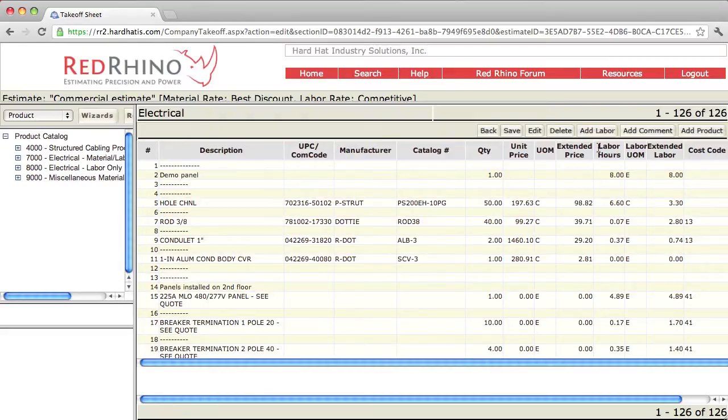Now again, use the Add Labor button for stuff like trenching, backfill, and compaction. If you have somebody working on the back of a trencher or using a trencher for trenching, you calculate how many hours it takes, and you input it using the Add Labor button. Same example I gave you with demo. You figure out or calculate how long it takes to do demo on a project. You come in here and manually input it using the Add Labor button.